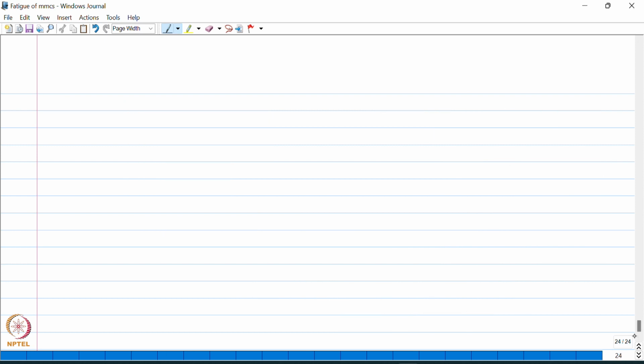The stress intensity in case of fatigue testing, as we have discussed before, is given by the stress intensity range delta K. And in long crack samples, it has been found that particles are debonded at low delta K values.